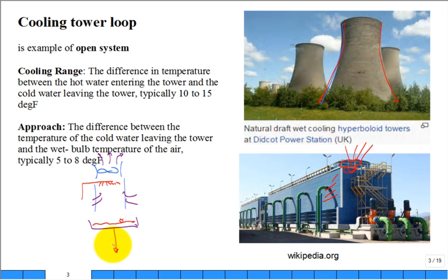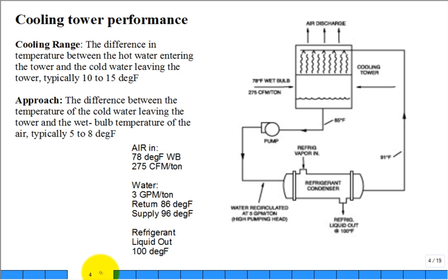There's a couple terms. I think I'm going to define these again. Let me see if, here they are on the next page. So here's an illustration of a cooling tower. Why do you want to throw heat? It's throwing heat to the environment, so you're coming out with some fairly warm water. You can ignore that temperature right there. You come up and spray it in, and then you have air discharge, mechanical draft, and you're bringing in air. All right, so you collect it in the basin. Typically, you put the pump way in the basement, if you have it. Put it at the lowest elevation so that it has a nice high suction head, so that it avoids cavitation in the pump.